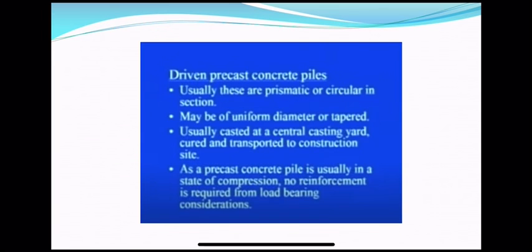Let us first have a look at some of the salient points on driven precast concrete piles. It is driven by some mechanical means, due to vibration or hammering. It has been constructed or cast at a workshop and transported to the site. So wherever there is a precast pile, its size and shape are fixed. You cannot alter them.